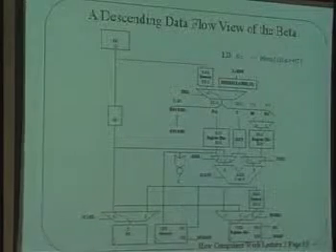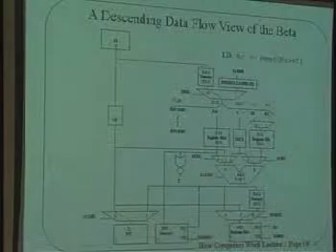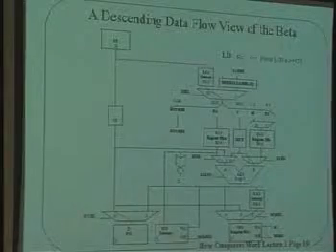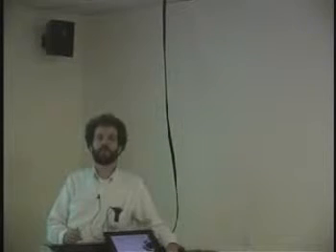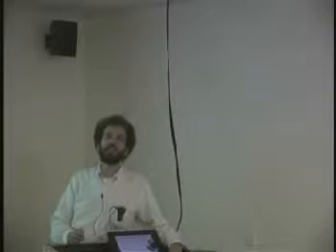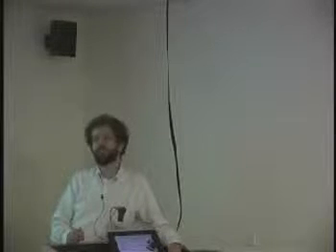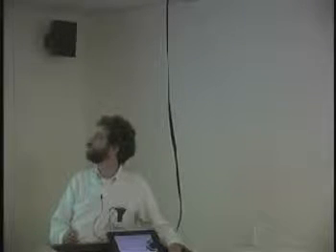Can you interchange things in slow memory without going through the register? No. And that's kind of a shame, except it turns out that most software doesn't want to do that. So towards the end of this class, we're going to talk about all kinds of trade-offs that we've made here, like why it is that we chose this structure as opposed to others. And so the structure here, and this is very typical of RISC systems, is allow a lot of things to happen in the fast memory and have a very sort of clumsy, slow load and store to move things back and forth. But we'll talk about why that is.